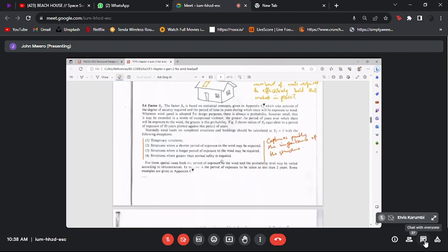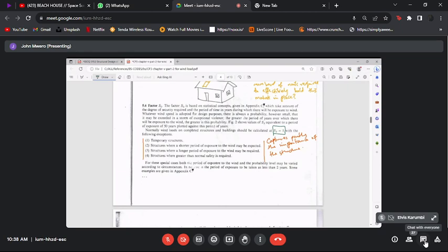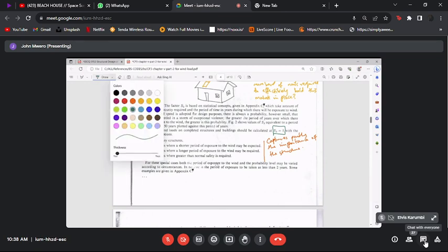S3 is a factor based on statistical concepts given in Appendix C. So there's an Appendix C in this standard for that. But generally this factor is adequate to assume as 1. And the statistical concept is one that we will talk about to some bit more extent in terms of earthquakes.